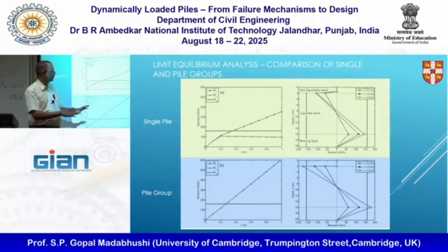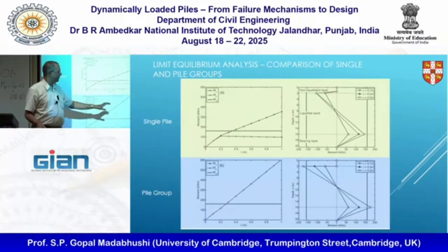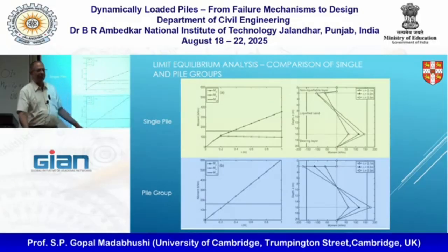Okay? Now we've got the proof, and we can also tell how much deflection it can tolerate by the time it gets there. This is all pure structural analysis. Yeah, we haven't done any magic with this. This is how much I can structurally deflect to get the failure or plastic moment hinge formation. Whether there's a bit of an esoteric question, where you can say if the plastic hinge forms within the pile, would you call that failure or not?